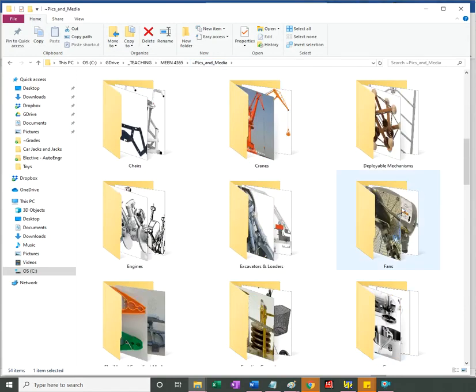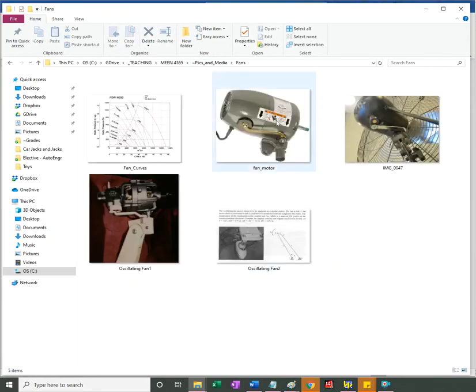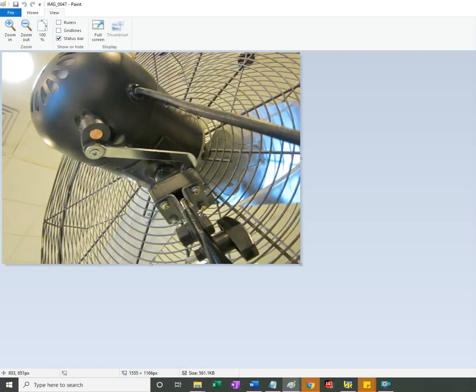But I was looking for, and I do have it somewhere, was, yeah, fans. The oscillation of a fan that is crank driven, and this is a drag. Is it a drag link? Yeah, drag link, Grashof 1 drag link. But you want to get a certain amplitude to the oscillation of the fan for continuous crank input. How do you do this?